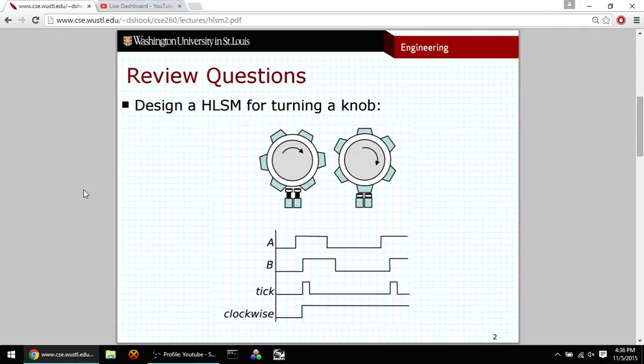Could we compare the previous button state to the current button state, right? Is that kind of how it works? So if both buttons together are not equal to the previous buttons, we'll take this transition, right? If both of them are not equal, then we'll take this transition. Do we need to do anything else? Do we need any actions on this transition?